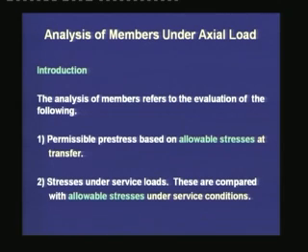Earlier, we had known that the load stages in a prestressed concrete member can be divided into several stages. The first one is the stage at the transfer of prestress. Second is the stage during transportation of the prestressed member from its casting site to its permanent position.